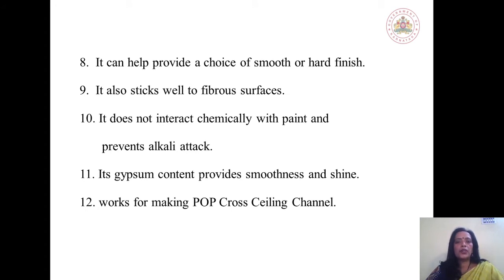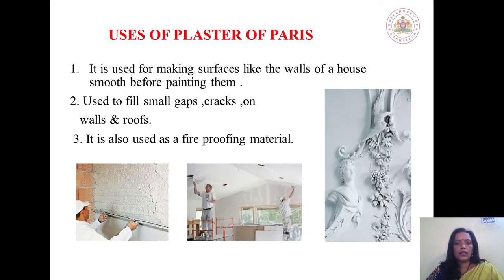It also sticks well to fibrous surfaces. It does not interact chemically with paint and prevents alkali attack. Its gypsum content provides smoothness and shine. It is also used for making POP false ceilings. These are the advantages of POP.